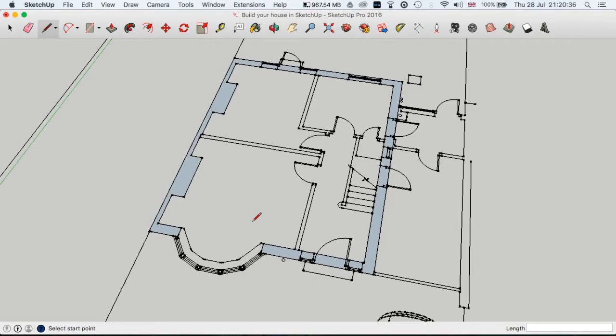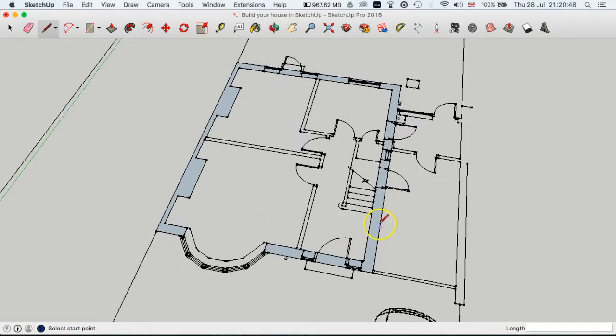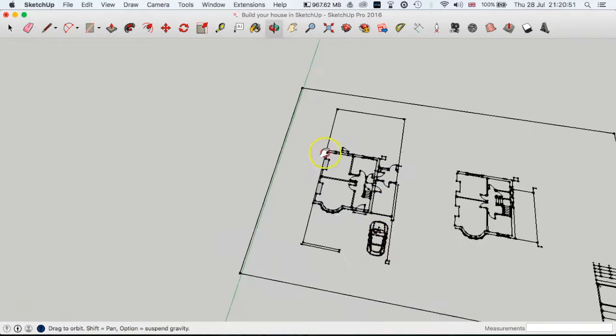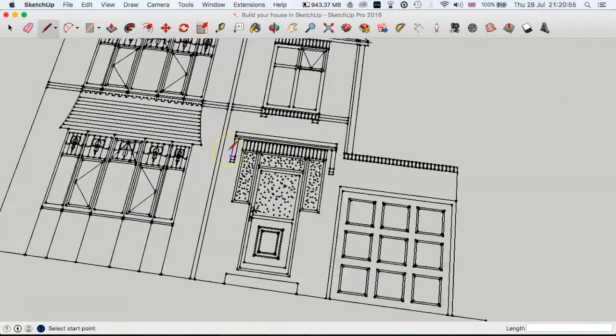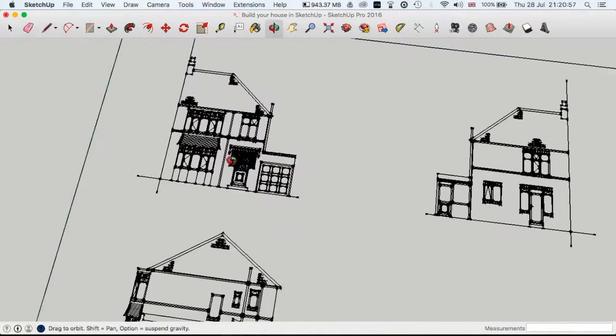Now one thing you need to remember when you're building and measuring your model is you need to get the ceiling heights in every room. So again, the easiest way to do this is with a digital tape measure. What we're going to do on this one is see if actually the heights are on. It might not be. All the elevations. They're not,